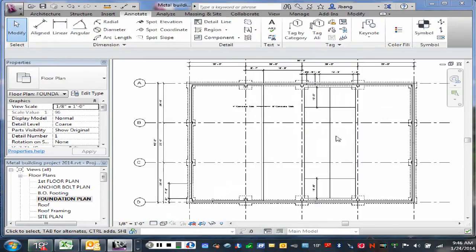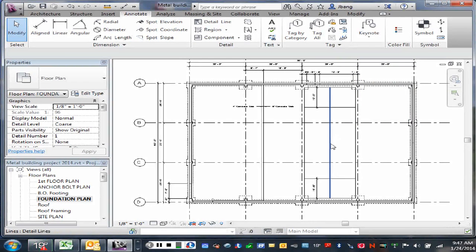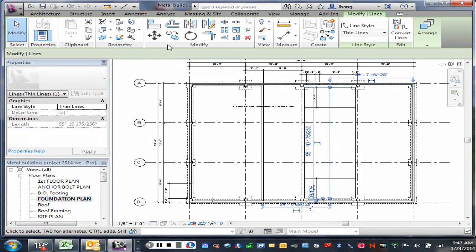Okay, on this center line, I want to create a flat spot in the bottom where the floor drain is going to sit. Now the floor drain could be a 6-inch wide floor drain or an 8-inch wide floor drain or a 12-inch wide floor drain. So there's different widths of floor drains. I'm going to offset this line 6 inches each way.